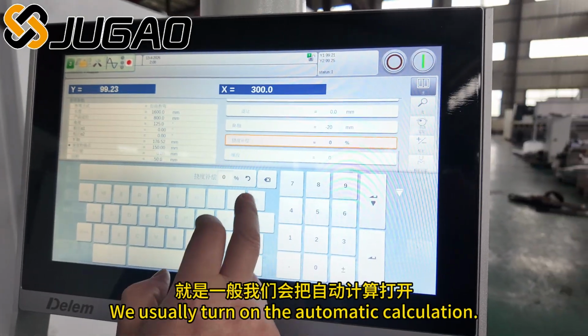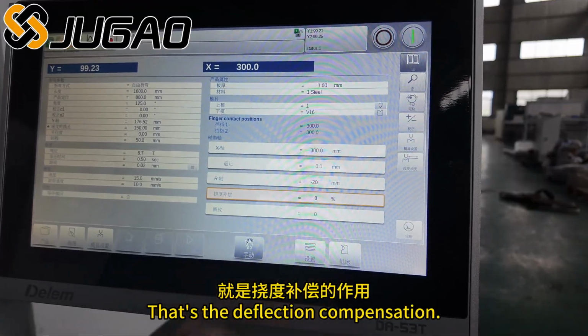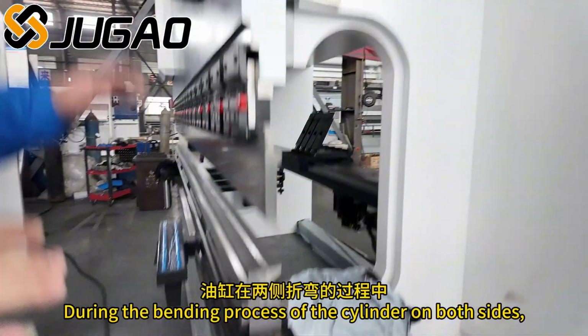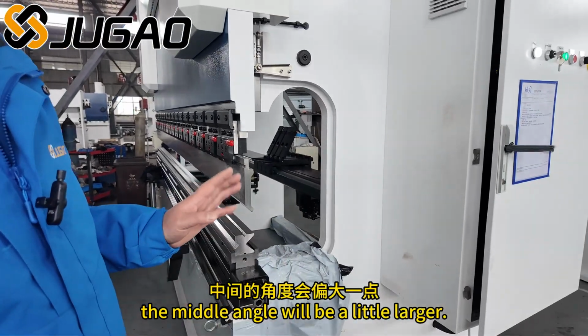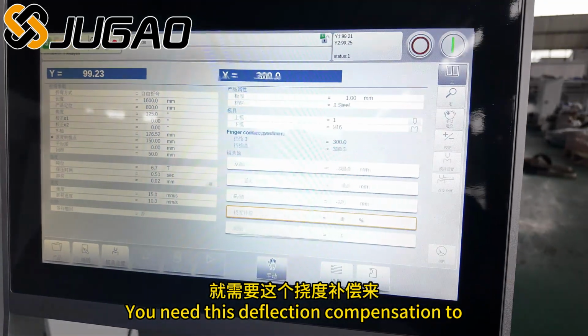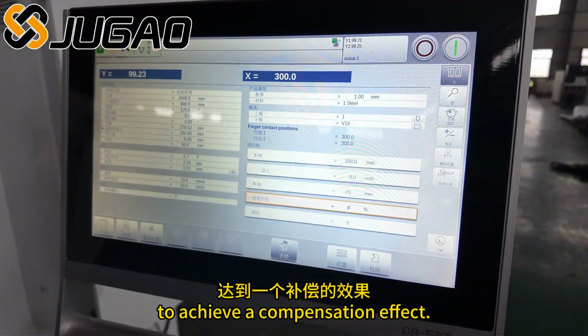Deflection compensation. We usually turn on the automatic calculation. It's this deflection compensation motor. During the bending process, with the cylinders on both sides, the middle angle will be a little larger. So you need this deflection compensation too, to reduce the angle in the middle and achieve a compensation effect.